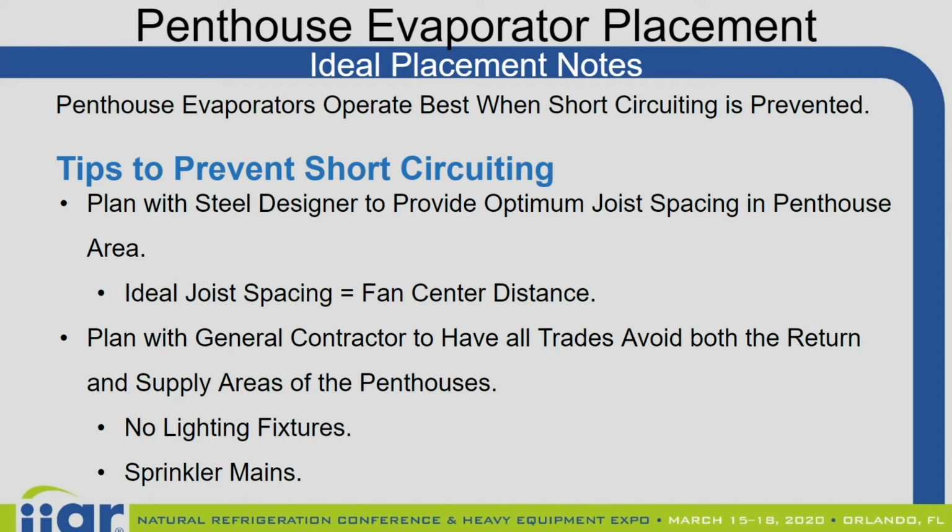Short circuiting of a penthouse happens if there's either inadequate natural separation between the discharge airstream and the return airstream, or there can be obstructions.